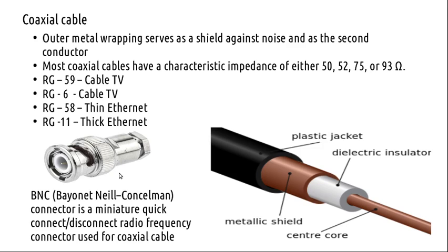The CRO probe connector, you will say. It is technically called a BNC, Bayonet Neill-Concelman connector. This is an invention from the World War II times. It has a lock which fits into the device and locks there. They used this first in naval ships, where the equipment is subject to rough seas and constant shaking, so that it won't get detached.